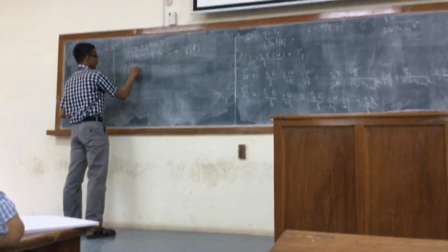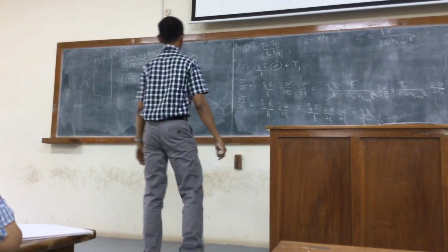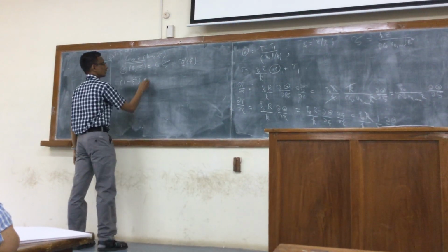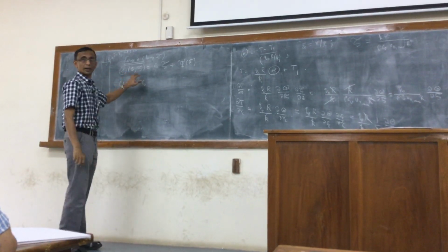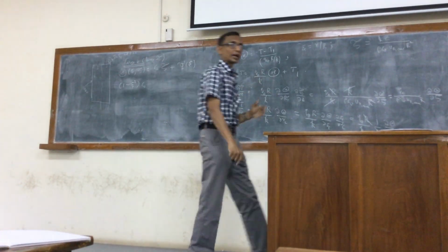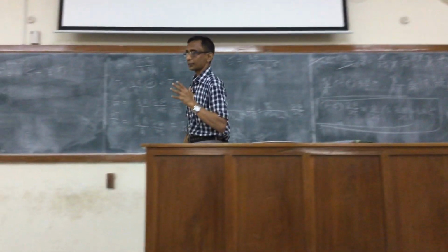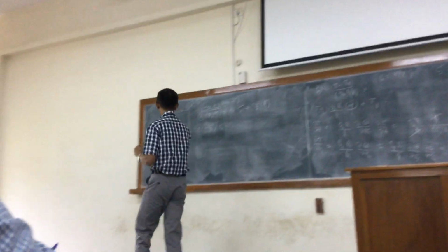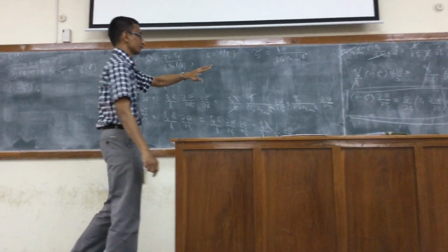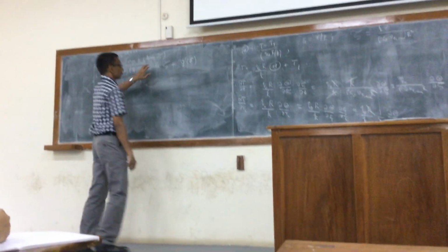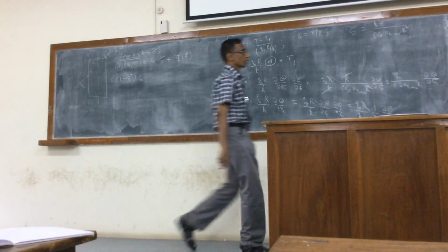So we get 1 minus psi squared times d theta by d zeta, which is c naught. I'm writing that equation now. We're neglecting viscous dissipation effects. We're only considering the large zeta solution, which means the large z solution. So if I evaluate the left hand side, I have 1 minus psi squared, and d theta by d zeta will be a constant c naught, which we have to determine.